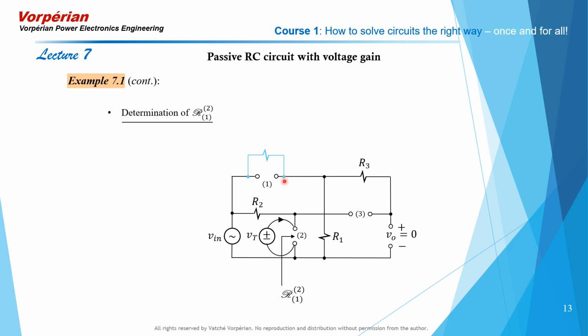And now you see that when you null the response V0, in the presence of this arbitrary resistance, you are nulling the voltage as before across R1, since there is no voltage drop across R3, which means that there is no current now through either R1 or R3, which means that there is no current through this temporary resistor R that you're introducing, which means that the voltage at this node is the same as Vin.